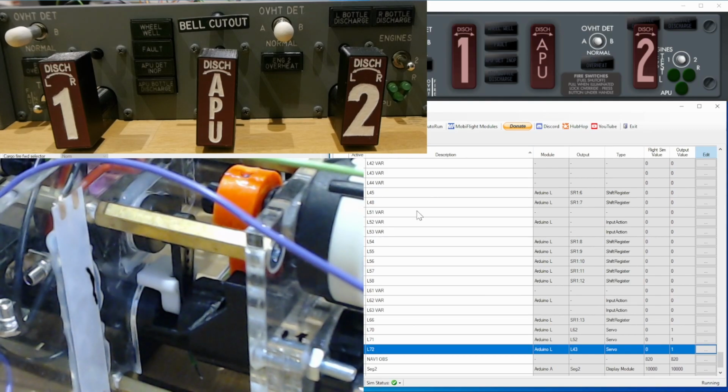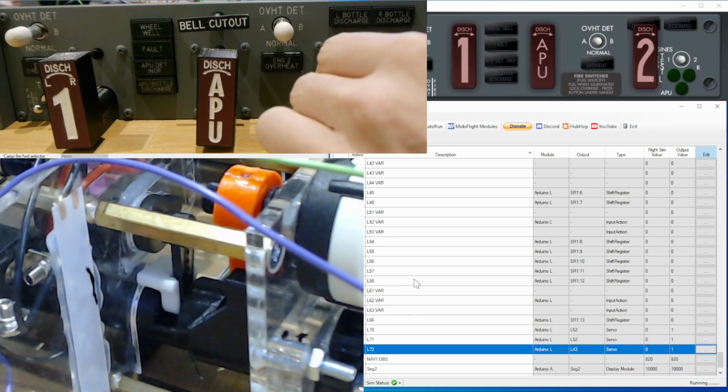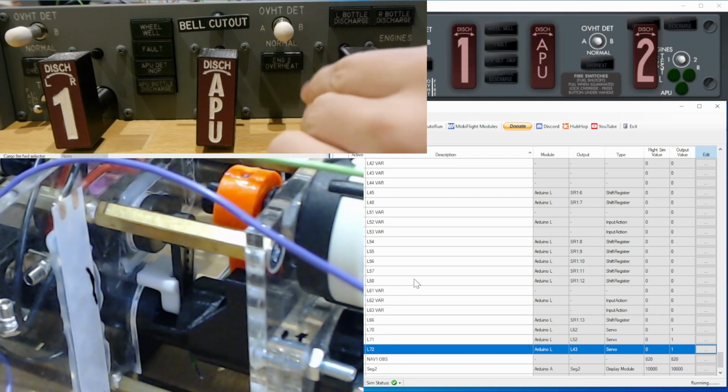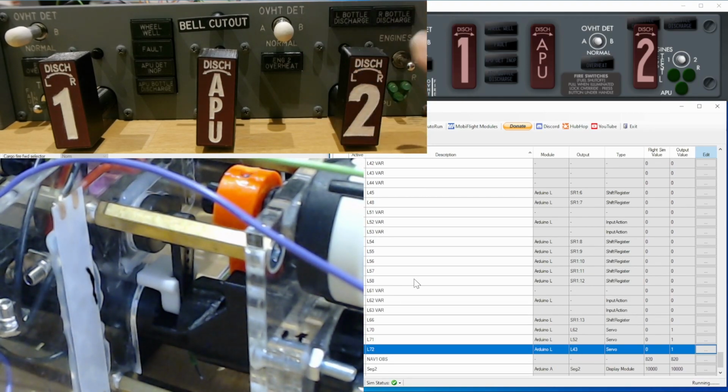So this is the normal situation in the cockpit: the handle is blocked and I can't pull it out. So don't try this too much. It's only a plastic handle and not a metal one. When you feel that the handle is locked, then you should believe it is locked.